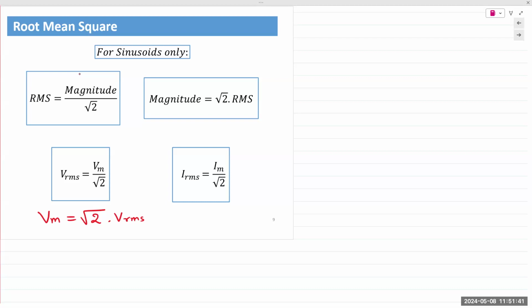So then the question I would ask is, are power outlets and all the voltages that we refer to in real life, are they RMS or are they peak? Here's a hint. RMS value is describing one value for all instants in time, one single value. Whereas peak values are only describing one value at one point in time. So if you're describing a peak value, you need an additional descriptor with it, which we don't. So again, 120 volts, is it peak or is it RMS? RMS, because it's describing an RMS. So unless explicitly stated otherwise, all values are always RMS. All measurement meters, all analysis is always RMS values. It's never peak. If it's peak, it will be stated as peak value or magnitude. Otherwise, it's always RMS.